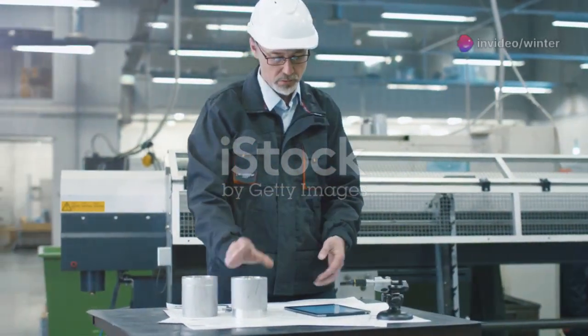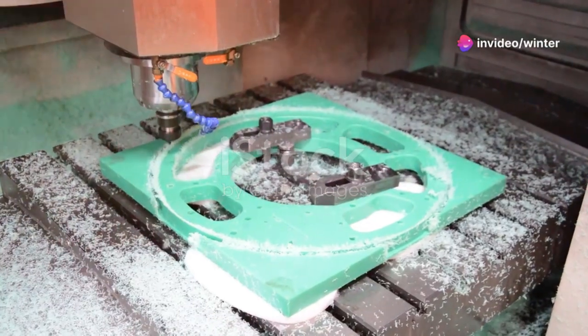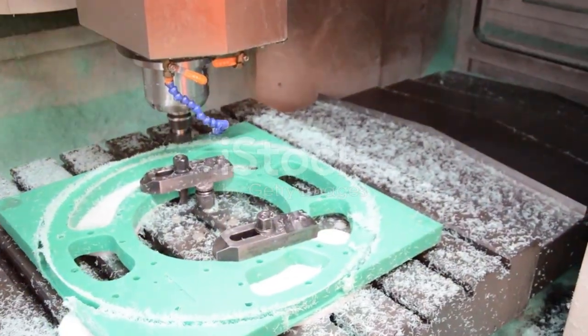Mold material choice is a major cost driver. Match it to your production needs. Aluminum molds are fast and cheap to machine, perfect for prototypes and low-volume runs. But they wear out quickly, good for a few thousand parts, not millions.